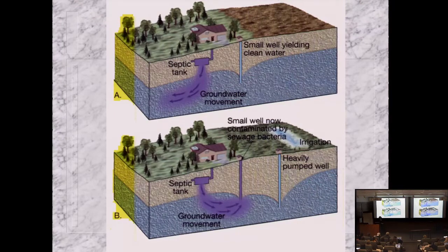When you have a septic system, typically you also have a groundwater well, and nobody is looking over your shoulder to make sure that you're supplying yourself with fresh water. So I just put this up briefly to show you that the textbook way of doing things is you have a gradient on the groundwater. You put your septic system down gradient of your well. So you're drawing clean water from your well, and then even if your septic system is improperly functioning, it's going down gradient. Water will never go from low to high head.